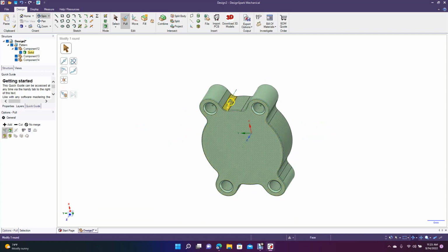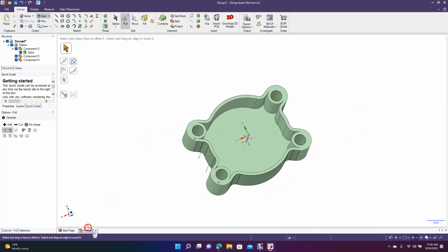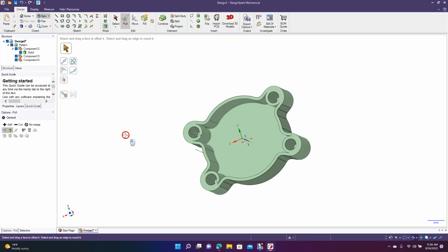Then in order to add fillets here, we did a Control A, which selected all the part, and then we came up here and did combine, so it combined these with this. So we were able to put our 2mm fillets in here. Then we went ahead and shelled here, the bottom. We did a 1mm shell. Then we created a fillet around these sharp edges here to prevent the model from cracking.